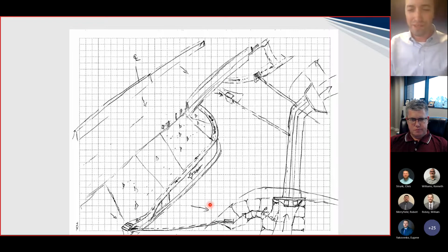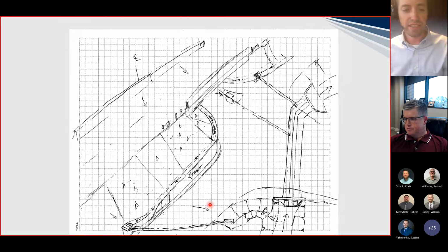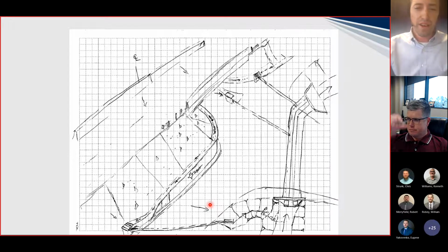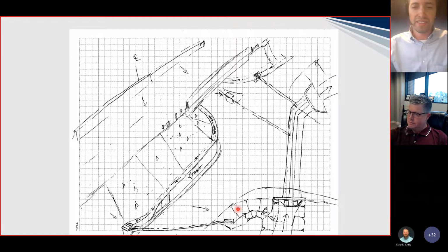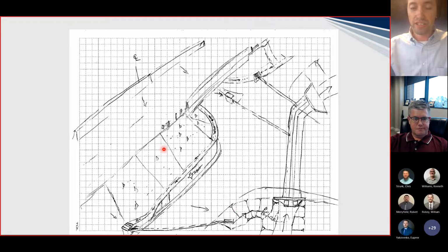So I hope you can make out what this sketch is. I put this together to try to illustrate some of the complexity of roadway drainage and to help start thinking through how we approach developing our drainage design. I like to think about, if I was a drop of water, where would I go? You really just have to take segment by segment of whatever you're designing and think through in detail, cross-referencing a lot of the roadway sheets, bridge sheets, retaining wall sheets, and cross sections, but starting with: where am I trying to take this water to?